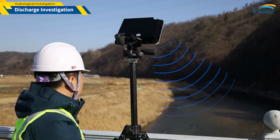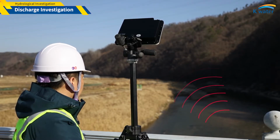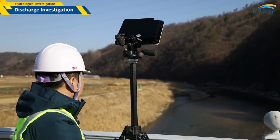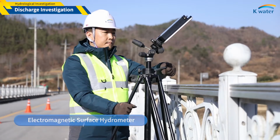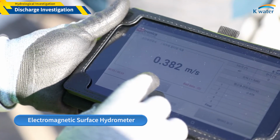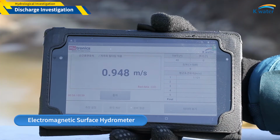The electromagnetic surface hydrometer uses the Doppler effect of the reflected wave to measure the flow velocity by generating electromagnetic waves to the water's surface. It consists of a hydrometer, a tripod, and a user terminal. Fix the hydrometer to the tripod and connect the user terminal to measure the flow velocity.